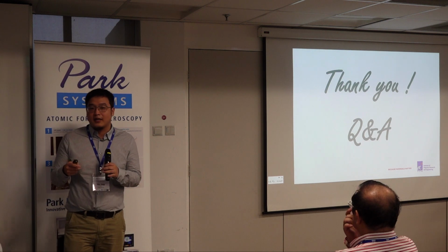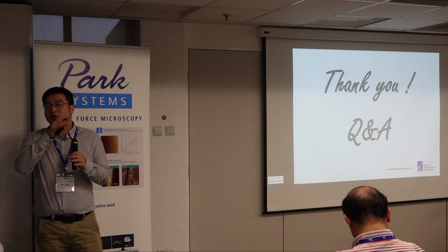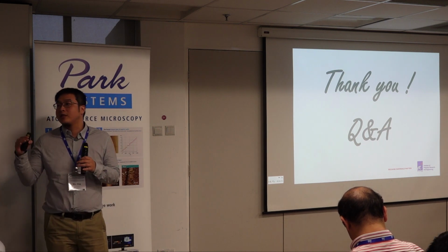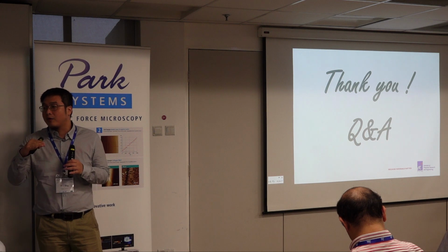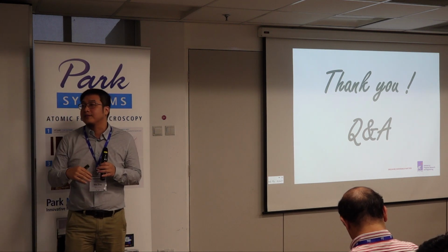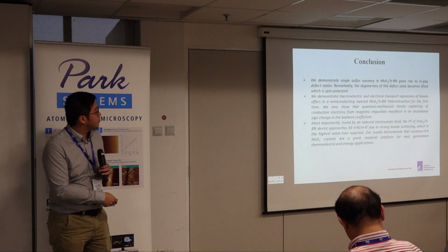Yeah, but because you can see the mobility change, right? For the silicon oxide side, actually the change is mainly screened by impurity scattering, mainly saturation. However, for hexagonal boron nitride, the mobility will decrease with temperature at low temperature. It shows the peak here.